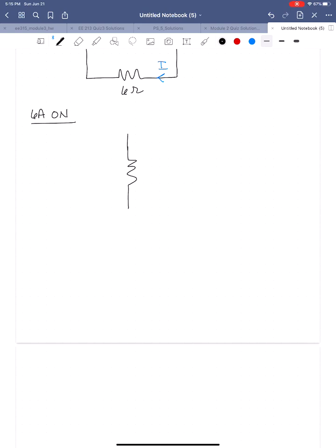Okay, so there's that 2 ohm resistor. Here's the short circuit where that 24 volt source used to be. We're open down to here, so the 12 amp source doesn't exist because it's open. Here's a 2 ohm resistor here. Here's this 2 ohm resistor here.